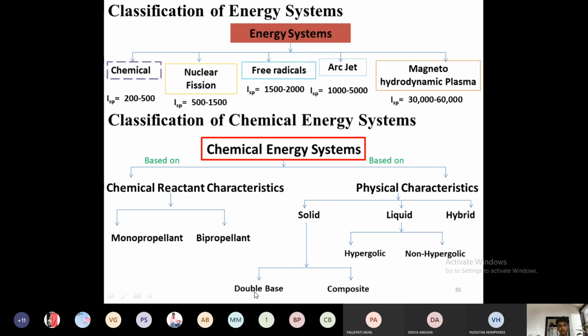Various phthalates will be available in order to give non-explosive characteristics, because when these propellant materials explode, it will shatter the rocket. So we need to deactivate that explosive characteristic. In order to do that, we need to add certain types of plasticizers like diphenyl phthalate in certain composition.